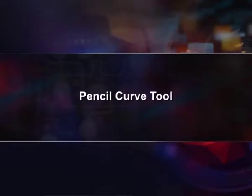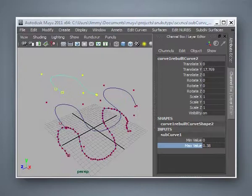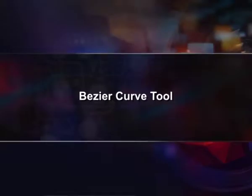Let us go to the pencil curve tool. The pencil curve tool method is useful for sketching a curve rather than creating it by placing CVs or edit points. The pencil method lets you create a curve as easily as drawing a line on a piece of paper. Next, we will go about Bezier curve tool.